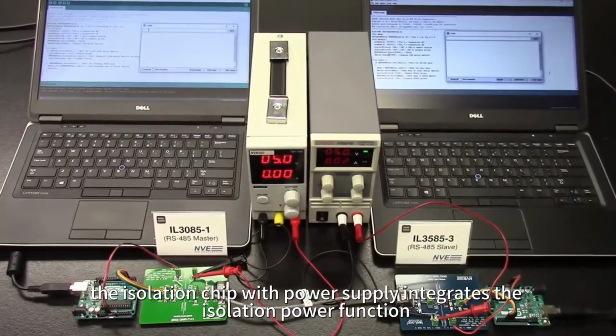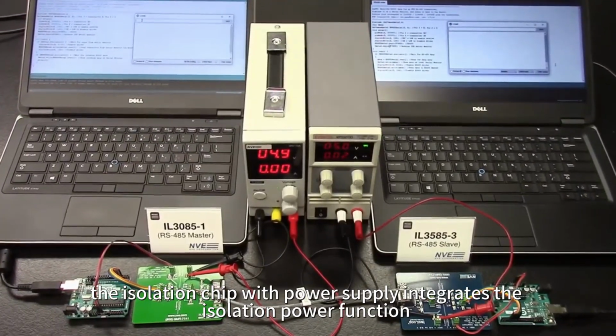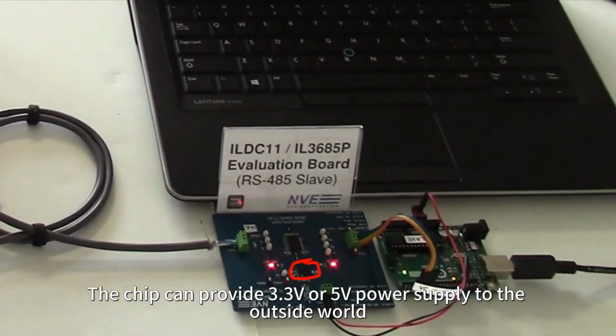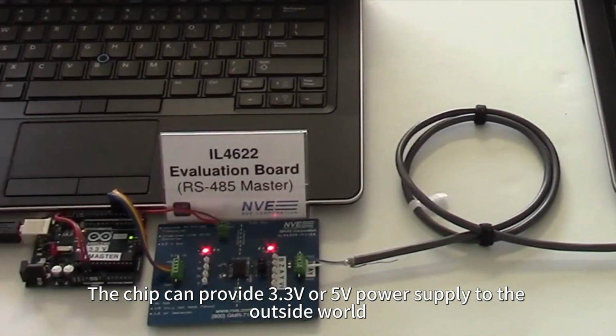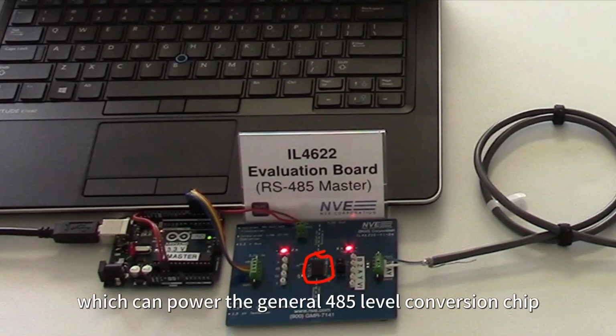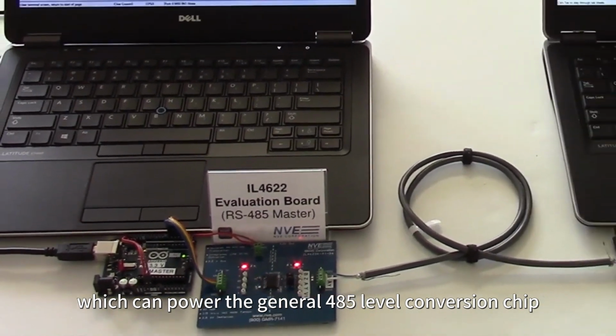In addition, the isolation chip with power supply integrates the isolation power function to realize power isolation and signal isolation in the chip. The chip can provide 3.3V or 5V power supply to the outside world, and the output current can reach 10 to 100 milliamperes, which can power the general 485 level conversion chip.